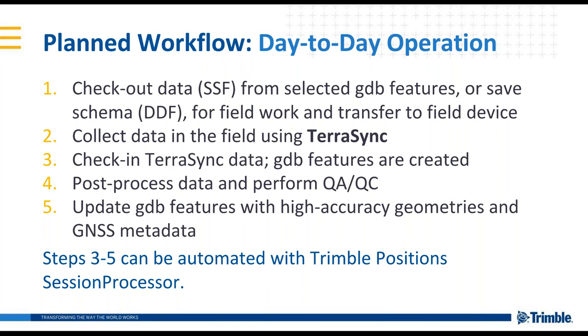If you're interested in new data collection only, you would take that DDF out to the field and transfer it to your field device, collect data using TerraSync, and when you come back, you would take that SSF that you collected, get it onto your desktop, and do a check-in. You would automatically create the geodatabase features, and you'd have your session to work with where you could post-process it, do QA/QC, and then when you're done, update your geodatabase features. This is just clicking a button, update your geodatabase features with high accuracy geometries and metadata.